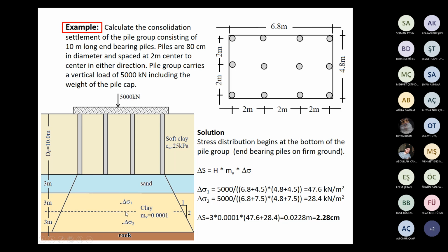We can use this depth as shown in the dashed line, and we can solve in one calculation. But generally, for thick clay layers, it's preferred to divide the clay layer into sublayers. Let us do this method in this example.